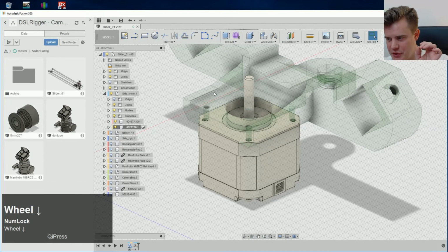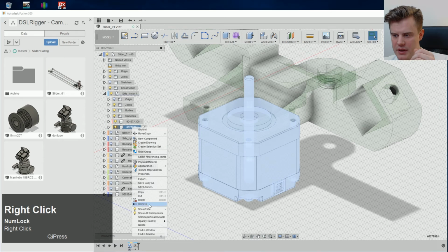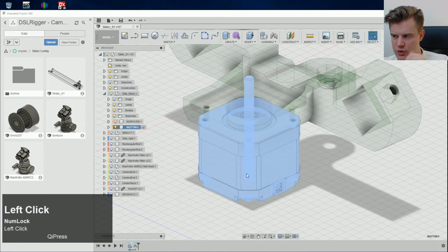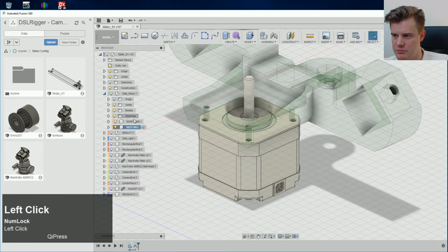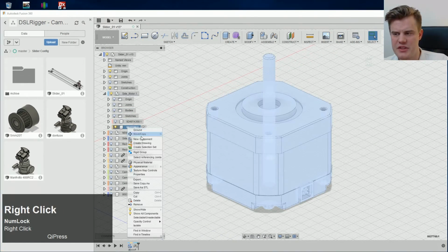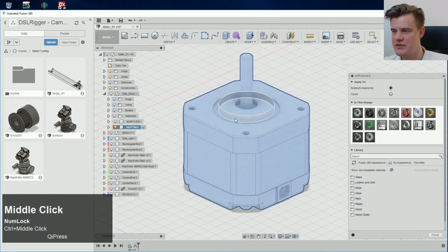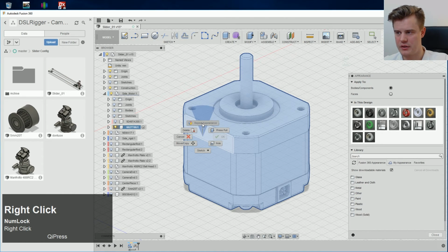And as a quick small tip, you've probably already seen this, but I want to show you how to texturize parts of an object. So let's just hide these here. So this is just the final thing, so thanks for sticking along. You click on materials, basically, right click, either there on the material, and then just appearances.